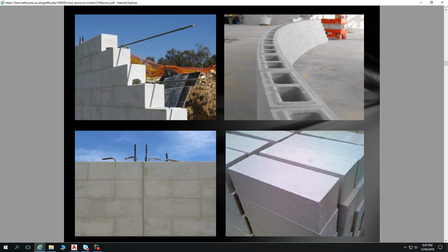And I guess it's because they're typically producing these blocks. Well, I can only guess really. I should have asked her why that is the case. But when you're pouring concrete slabs on site, you use different concrete in the winter than you do in the summertime. Because in the summertime, you want the going off of that concrete to be retarded. In the wintertime, you want that going off of the concrete to be accelerated.